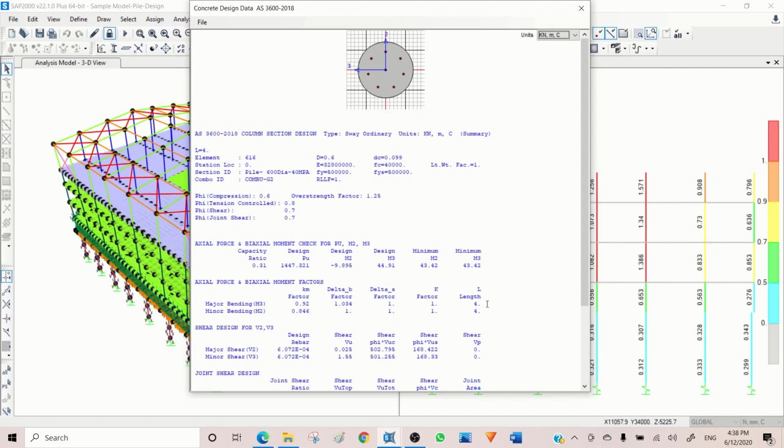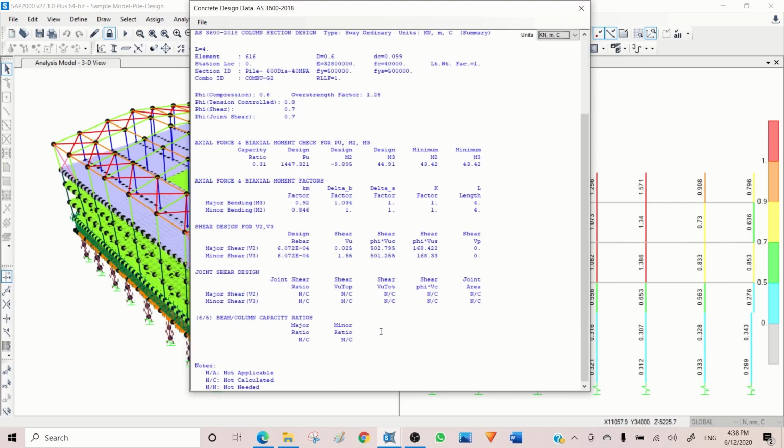The principle would be the same. Here you see the shear values and also the capacity, and based on that you can see the result and what design rebar you end up with. The shear capacity designed by SAP is actual values. As I said, it's not really a logical number of bars or spacing between bars.